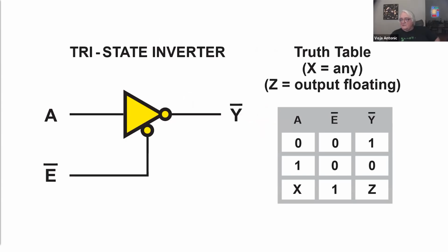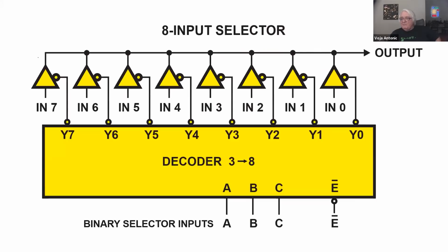This is the electronic view of the same circuit. You have one more input here, which enables or disables the output. When this one is passive, then the output is in high impedance here, Z output. Z is a symbol for impedance, so it's used for the high impedance state. Then it's simply disconnected. And you can use 8 buffers here.